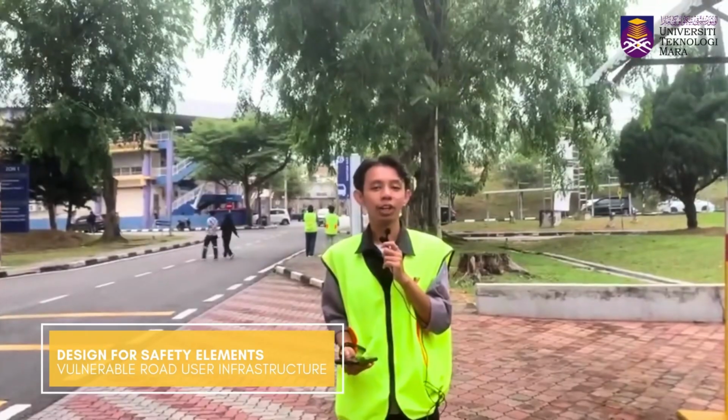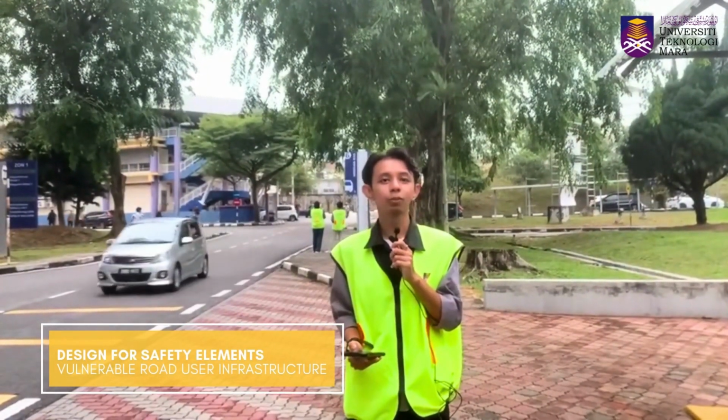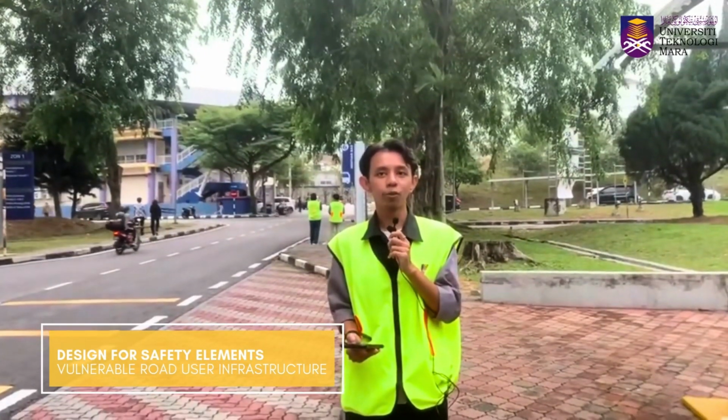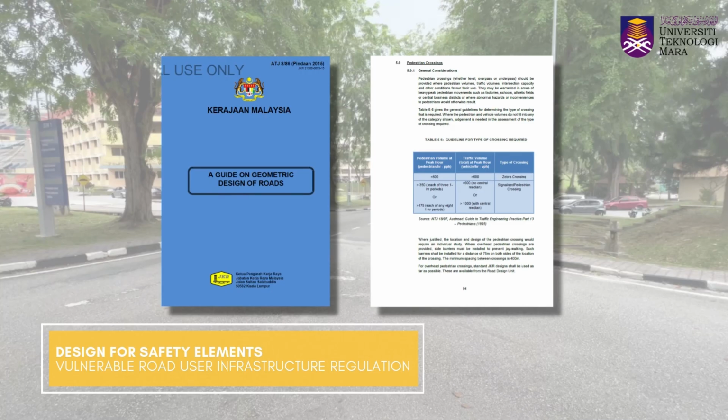Vulnerable road user infrastructure, or VRU infrastructure, refers to the physical elements or facilities designed to protect road users who are most at risk, which are pedestrians and motorcyclists. According to Arahan Teknik Jalan ATJ 8/86, a guide to road design for urban roads, it is recommended to install zebra crossings at conflict points, especially near schools, bus stops, public facilities, and residential areas. The crossing must have clear visibility, appropriate road signs, and warning markings ahead of the crossing.